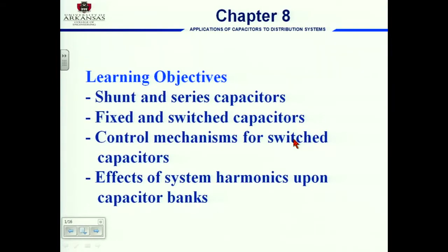So if you sense the voltage on the third phase, basically it gives you an idea where the back EMF for that synchronous motor is. And so they use that sensed voltage to know the rotor position.